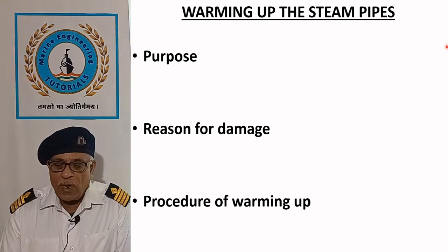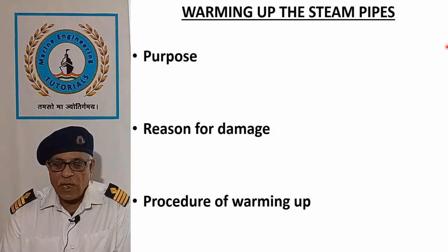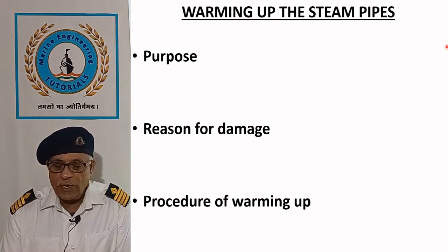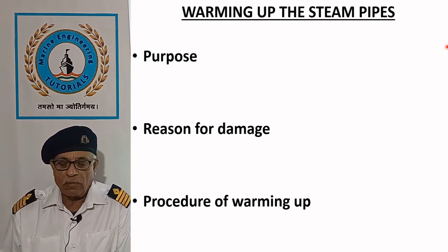For the purpose of warming up a steam pipe, a small sized warming up valve is usually provided, which acts as the bypass for the steam stop valve. Use of a warming up valve prevents the damage to the valve disc and seat of the steam stop valve, which can occur due to throttling of the steam and becoming wire drawn, thus eroding the metal.